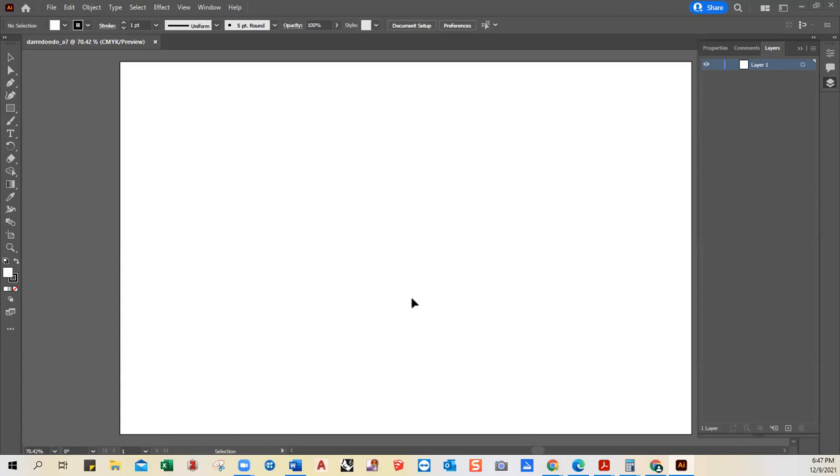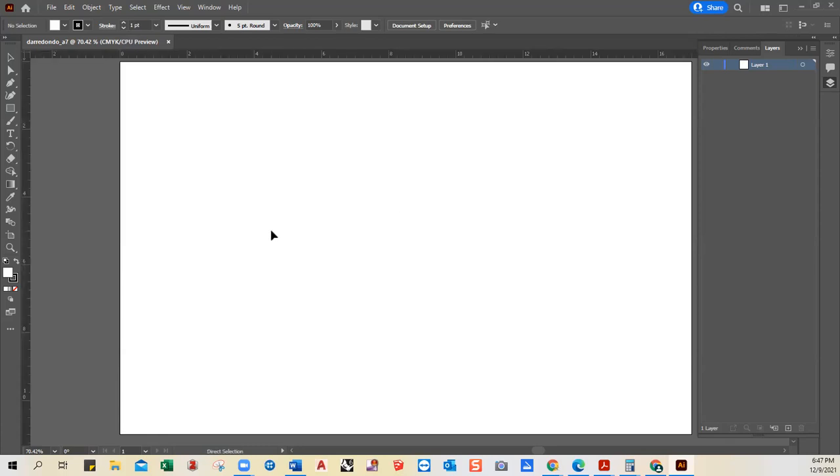A few more things when it comes to navigation here. If you want a ruler in order for you to measure margins, making sure that you don't go over, so that depending on your printer that you're using, that you have proper bleed, the keyboard shortcut is Control R, R as in rulers. So make sure, oh sorry, there you go, Control R. So you see the rulers here popping up.